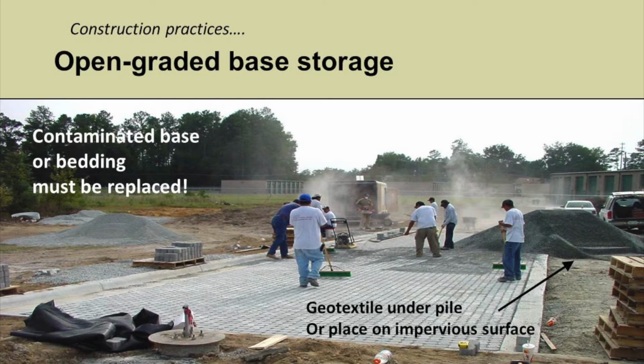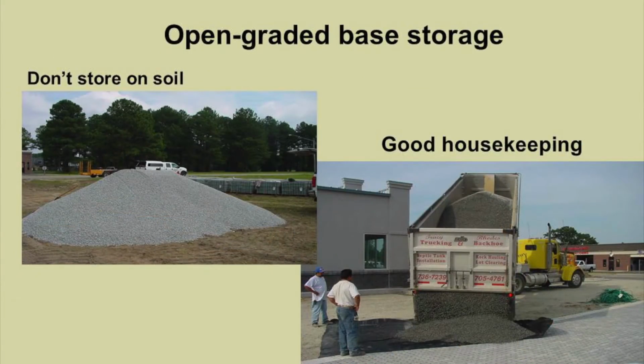Consequently, when he goes to pick it up with his bobcat or backhoe or whatever he's using to dump the material, he's going to get down as low as he can with that bucket. If you've got a geotextile laid out there on the site, that will help keep those aggregates separate and keep any fines from the material below from getting into that. So pay attention to that. Use, as you see in the lower right, good housekeeping processes here.